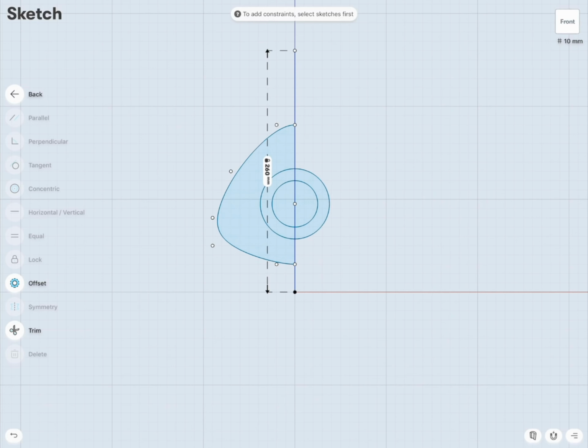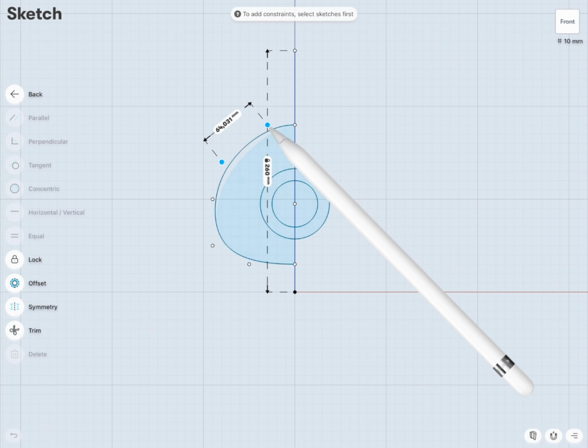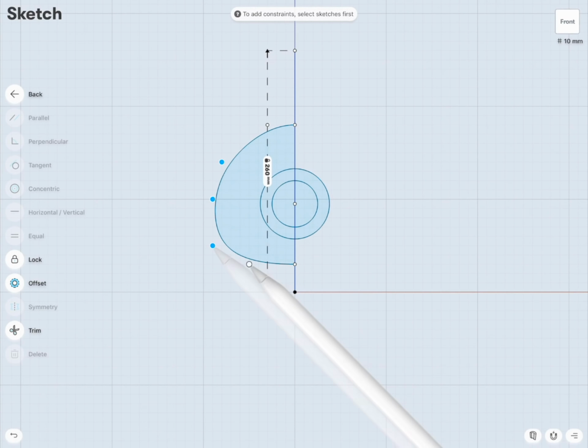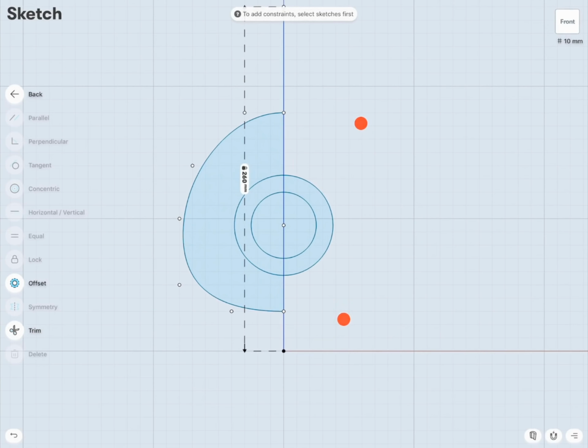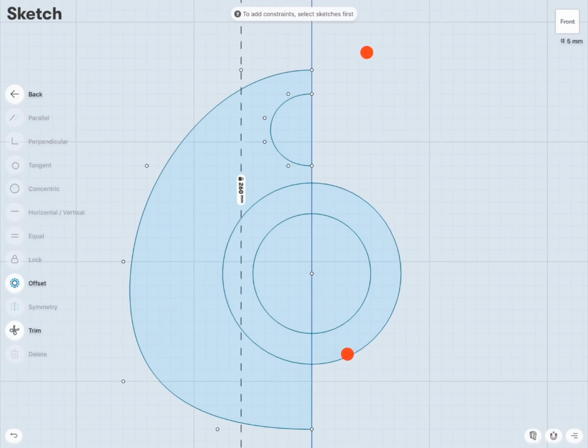The one thing you need to remember when you're sketching about half of the profile that is going to be mirrored is that the second and the first before last points must be exactly on the same line as the first and the last points and perpendicular to that mirror plane. Doing so will allow you to keep the curvature of the profile tangent when you mirror it eventually. Pay attention to the points I have just mentioned when creating splines with the intention to mirror them afterwards. There's no need to do it when sketching circles.